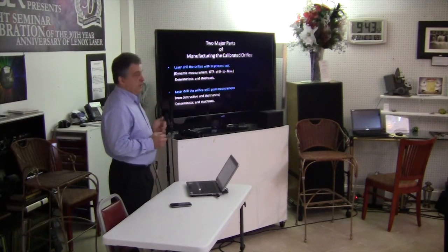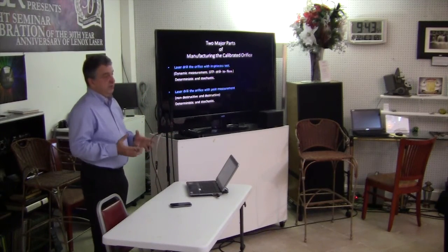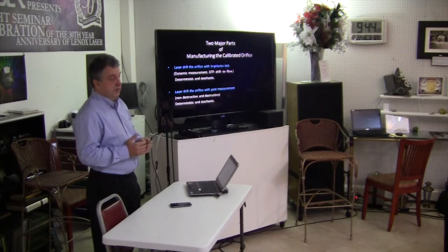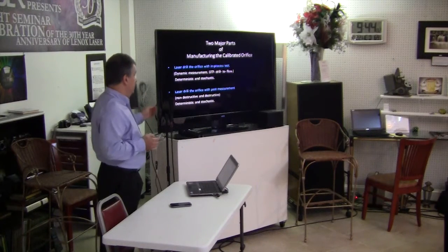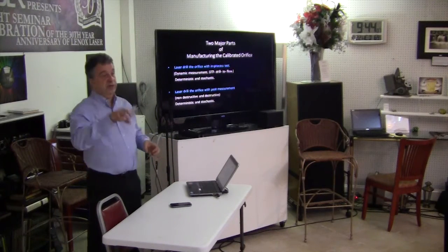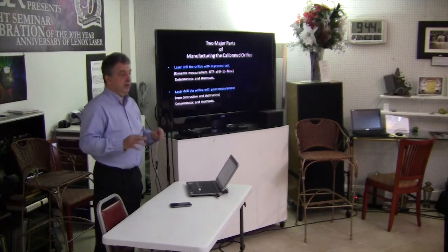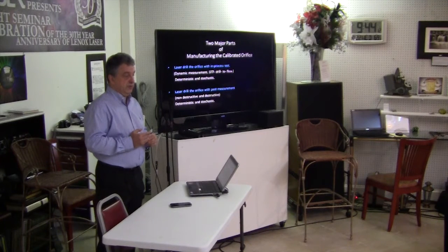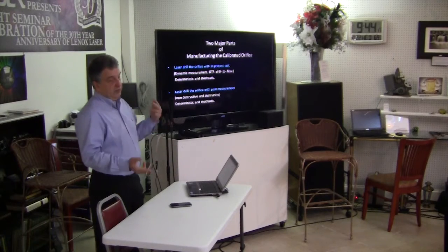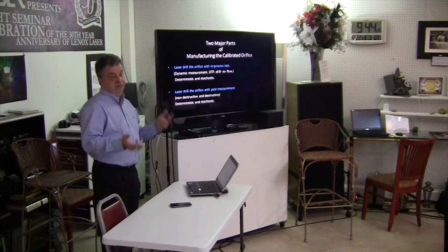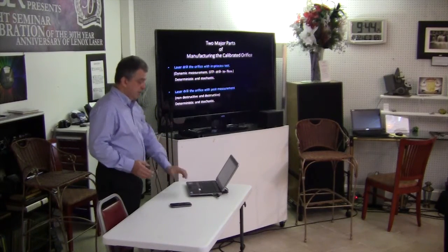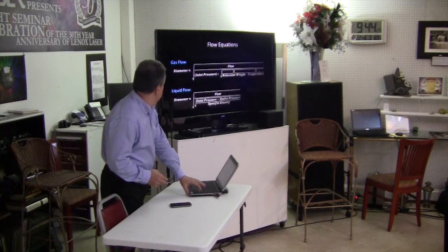So in this case, the post-measurement takes place. In other words, after the sample is done, we measure it and do the analysis. And those methods sometimes are impossible to do without destroying the sample. So we do the sampling, we design it by the request or by the reliability and repeatability of our instruments. And we know that we have to pull each 5th sample or 10th sample out of that, destroy it, and measure it, just to determine the long-term stability of our instrument there.